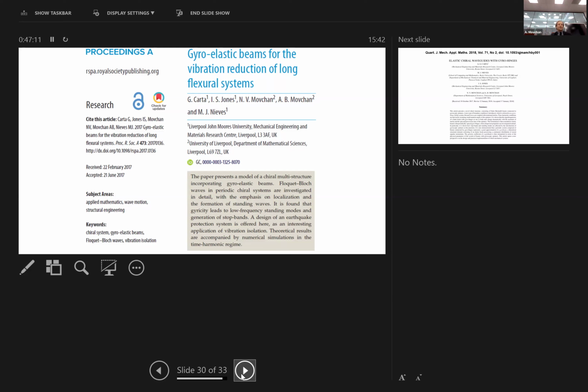And of course, when it vibrates, they know where the energy goes, and they dissipate it. So they have shock absorbers. And, well, not springs, but they have viscous shock absorbers. So that's how it works. Skytree. If you are in Tokyo, go and have a look, especially during an earthquake.